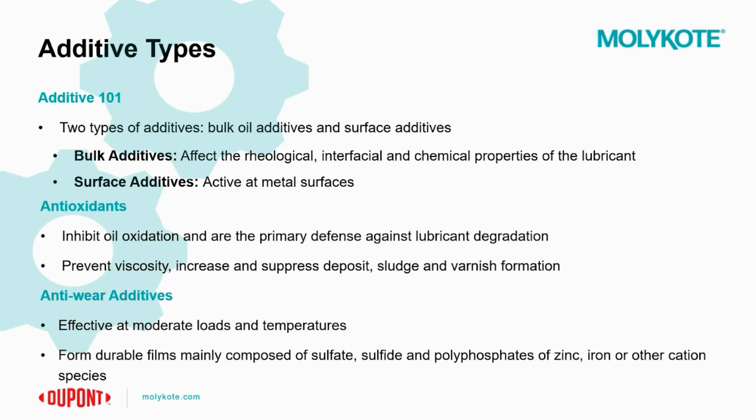And in the case of an application requiring anti-wear additives, the addition of the anti-wear additives ultimately will allow for the formation of very durable films, mainly sulfate, sulfide, and phosphates of zinc, iron, or other cation species. And these films will ultimately continue to be replenished for as long as the additive is present in the formulation. And you could see the use of these anti-wear additives in applications where you have moderate load and temperature.